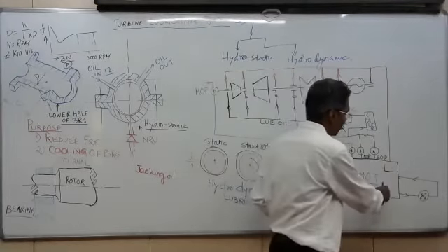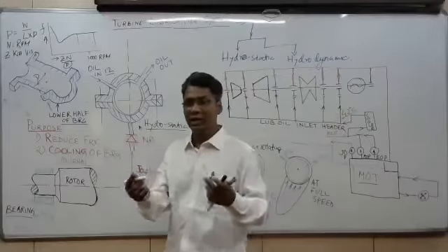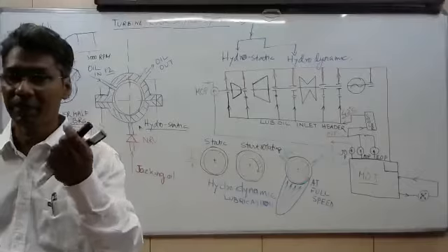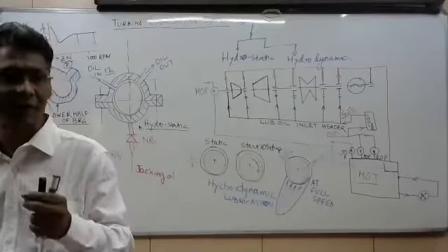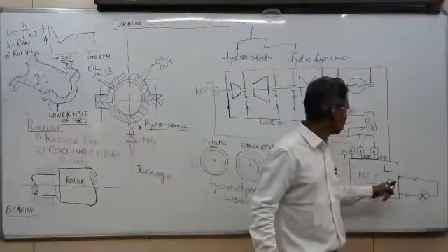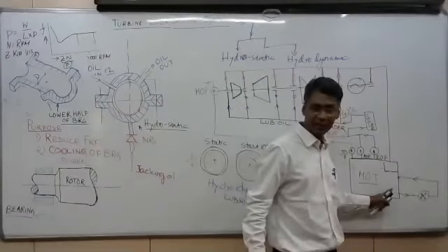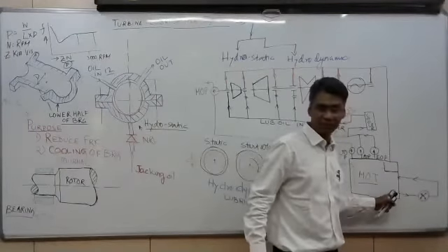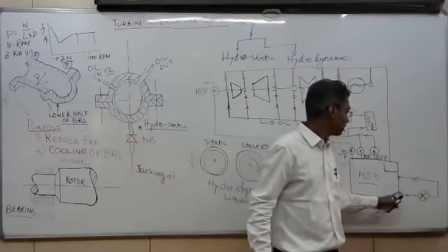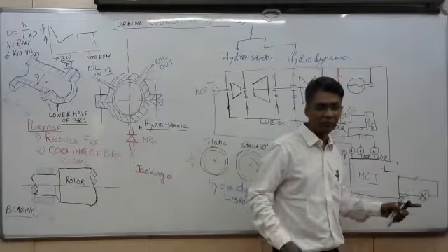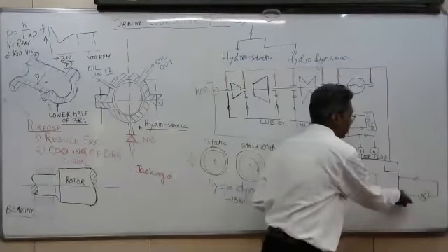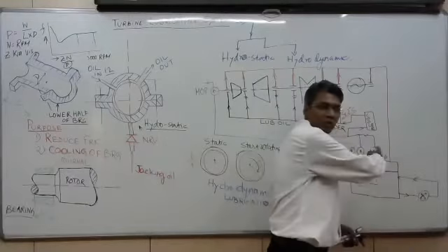Once it goes to the main chamber, the oil has some moisture in it, and some particles, metal particles, bearing particles, maybe very micro particles. To remove moisture as well as particles, we have a filtration or moisture removal system, called a centrifuge. Oil is passed through the centrifuge, a separate process. It takes the dirty oil and gives it back clean. It is a closed circuit.